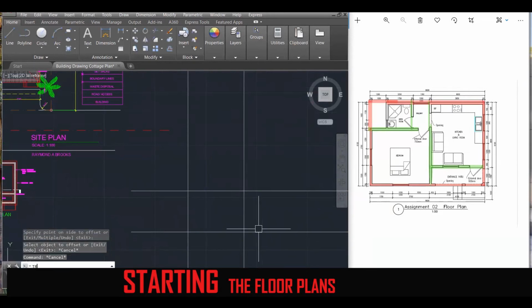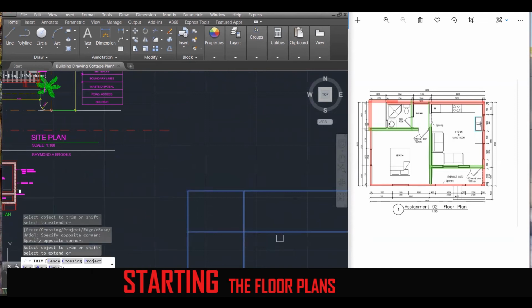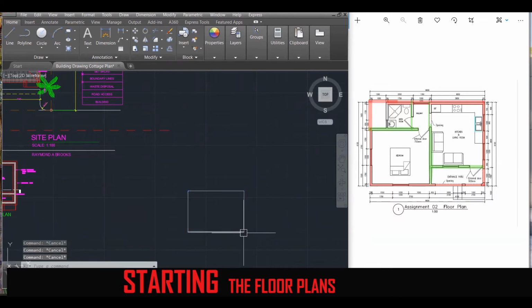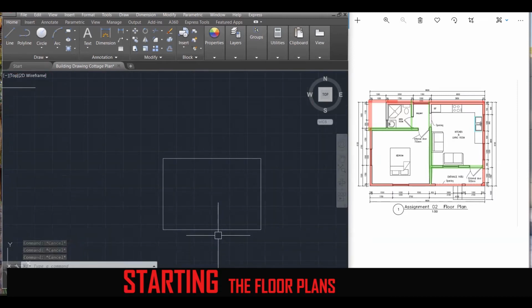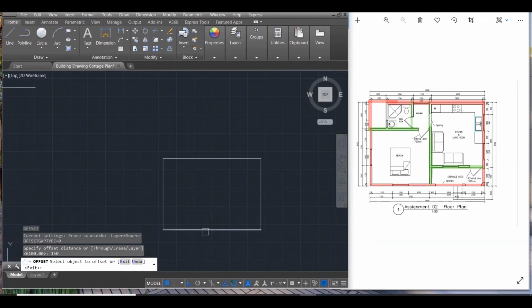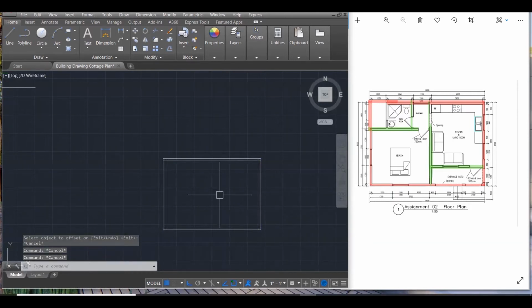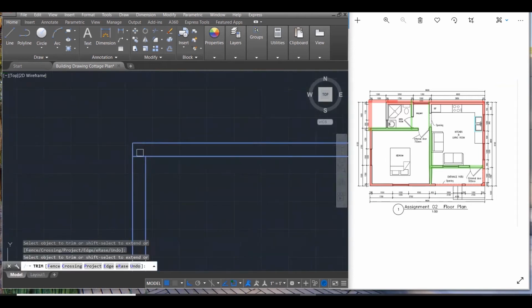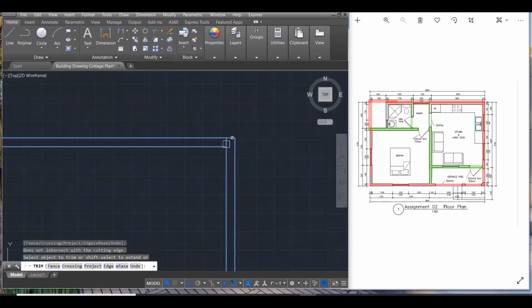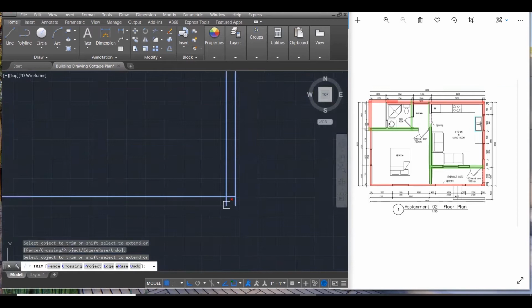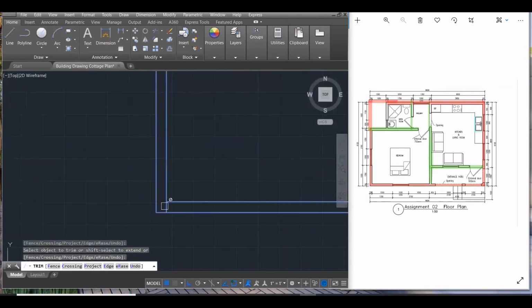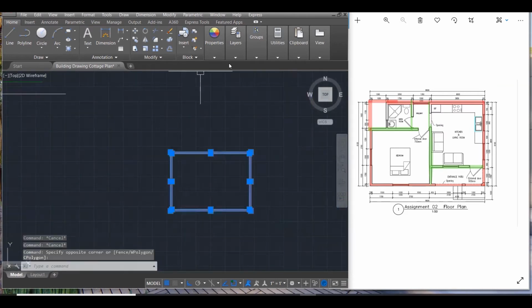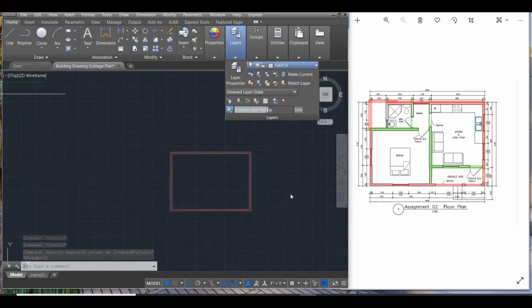Okay, cool. Now what I can do is trim. So I'm going to trim this, TR to trim. So I've trimmed that. And after trimming, I'm going to create a frame on the inside of 150. So I'm going to offset 150 and come in. Those are all in. Now, once I have my frame, I'm going to trim the inside of the frame. And then we're going to offset the internal walls. So I'll put these walls into the wall there so that everything will make sense to myself. Take that out of the hatch and put that into my outline there.